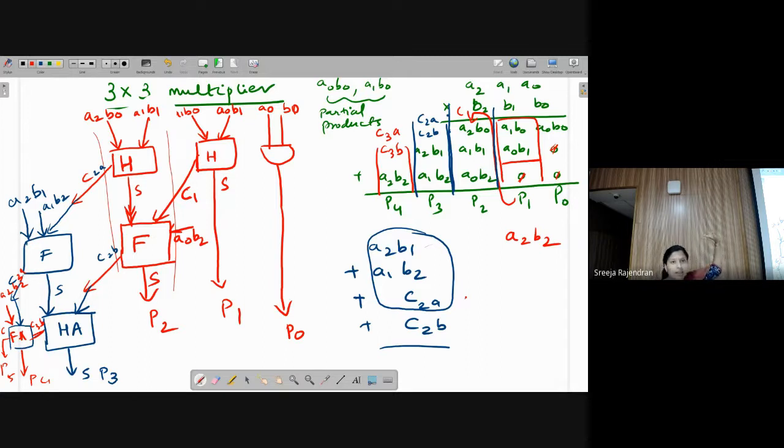This is already there in the 4 by 4 multiplier circuit also. If you see, it is done neatly. Now here you can see that in this last stage, where I have used this half adder and full adder, the carry from the half adder is not propagating to any lower stage. It is not going below, right? Is it going below? No. I have added it serially. Only when this carry is generated can this addition happen. So this carry needs to be generated so that this happens. So this part becomes a ripple carry adder.